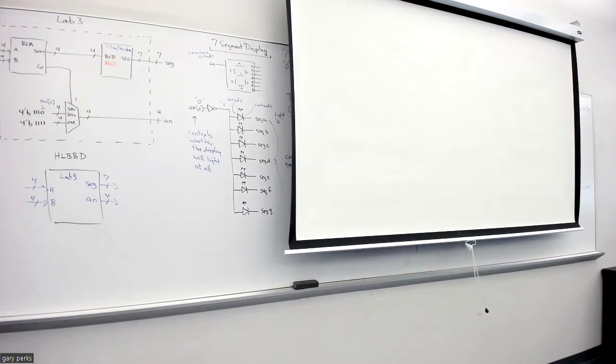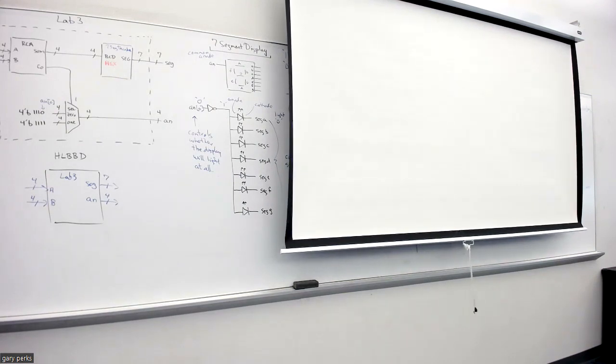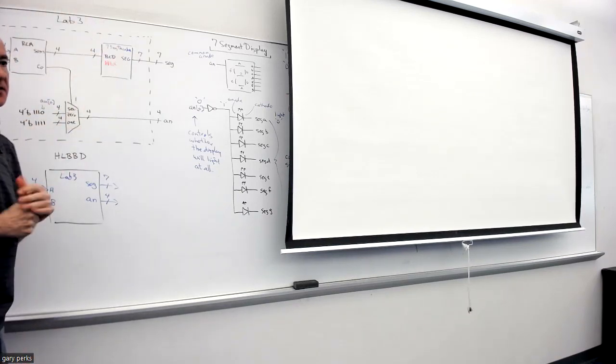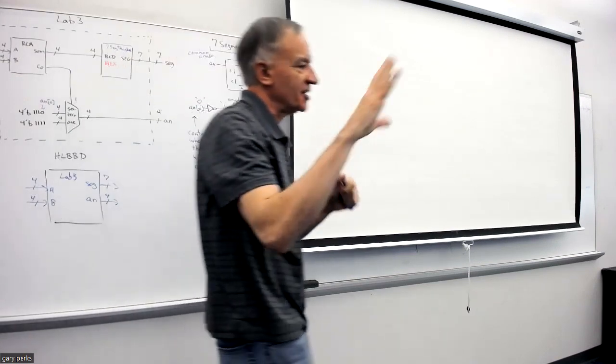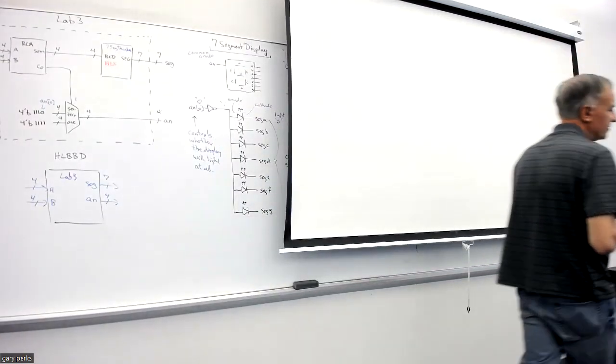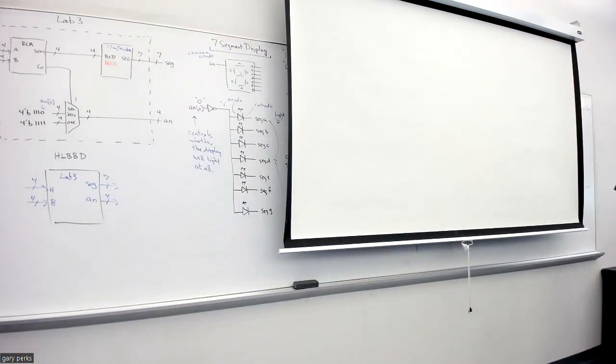So these test cases are for after you have a successful simulation for your mux and your decoder, and then you go to test the whole thing. And that's where, again, you got to make a structural model to connect those modules together.